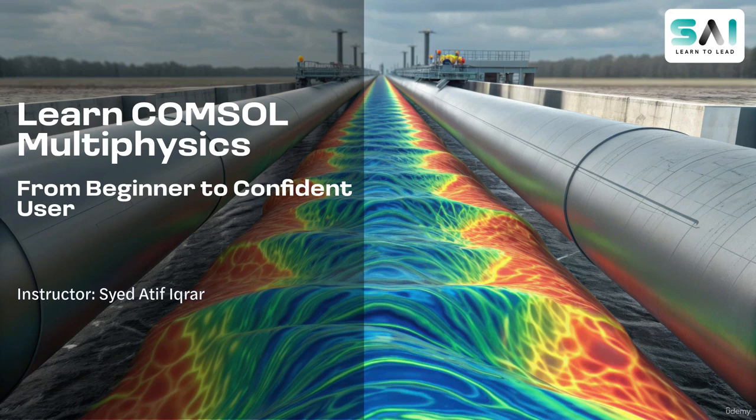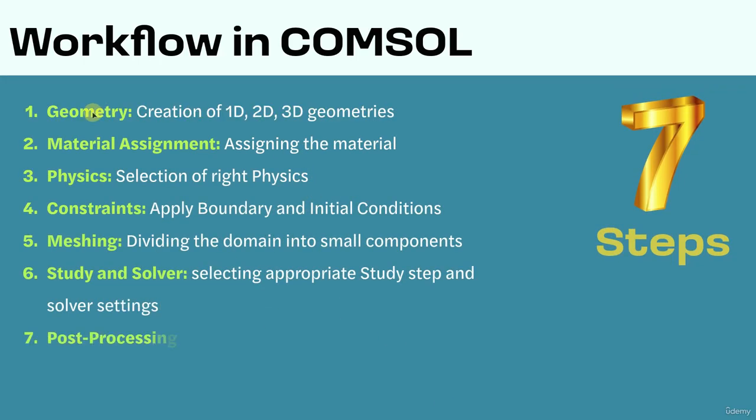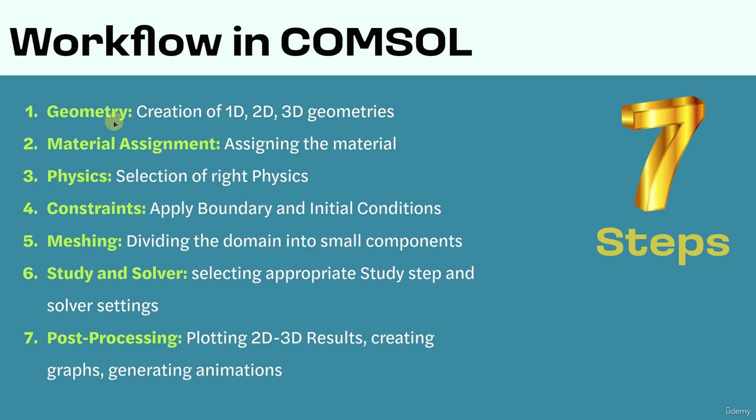In this lecture, you will learn a workflow to conduct any simulation in COMSOL Multiphysics. So let's start the lecture. This is the workflow in COMSOL Multiphysics. The first step in this workflow is creating the geometry, whether you are working with one-dimensional, two-dimensional, or three-dimensional domains. So the first step is to create the geometry in COMSOL Multiphysics.